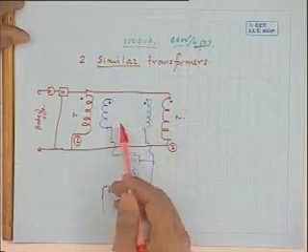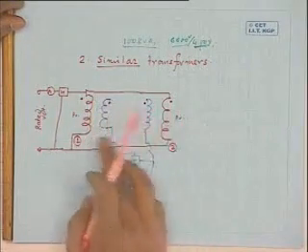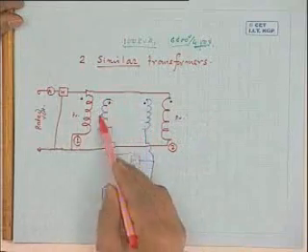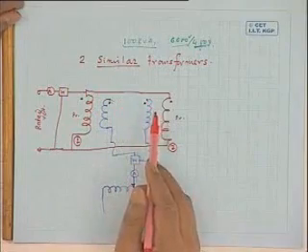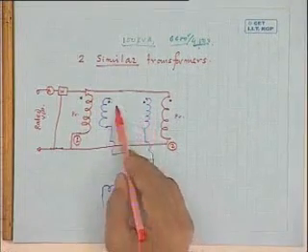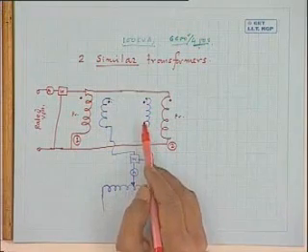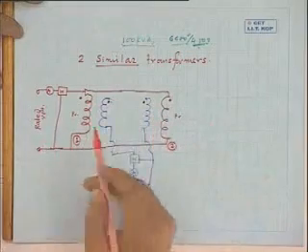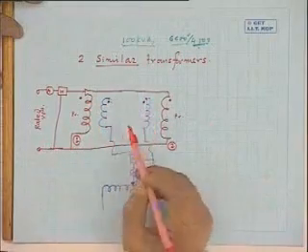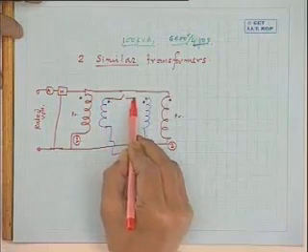So sometimes, without doing a polarity test beforehand, you can carry out the test if you remember this particular fact: you connect these 2 primaries arbitrarily in parallel, connect this way and just measure this voltage. What could be the other alternative? Twice this voltage will come if the dots are here. So one way of doing it, you do the polarity test first, then correct it.